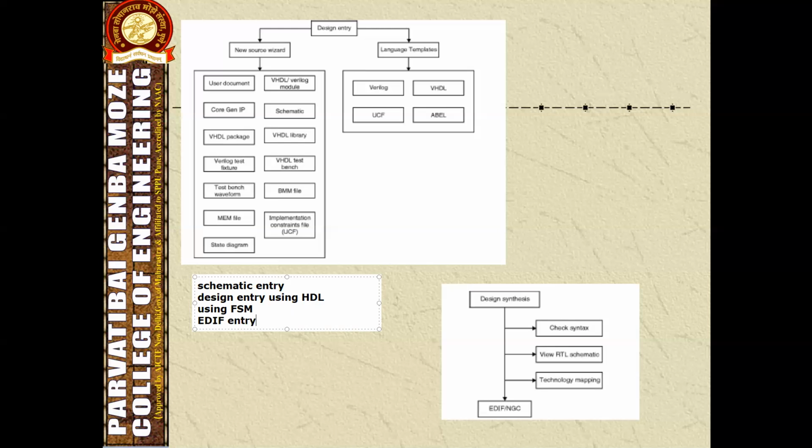The hardware description languages were originally developed for circuit modeling. Nowadays, these are used for complex hardware design. In this, the design is represented in the form of a coding template using the syntax of the HDL, and the different HDLs used in practice are VHDL, ABEL, and Verilog. For finite state machines, the design can be entered using the state diagram of the sequential circuit, and the CAD tool can be used to draw the complete state diagram on the personal computer and simulate it for the required result.